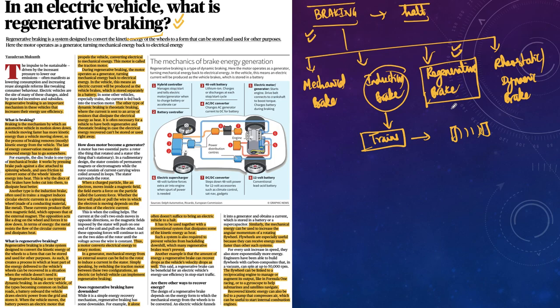And inside this magnetic field which is generated between these magnets attached to the wheels of the trains, whenever we apply a brake in these trains, a metal will be moving and it will be disturbing this magnetic field of the magnets, and this will produce an opposite eddy current. So due to the opposite eddy currents or opposite force which is generated, this will stop the vehicle to a halt. So this is how induction braking system works.